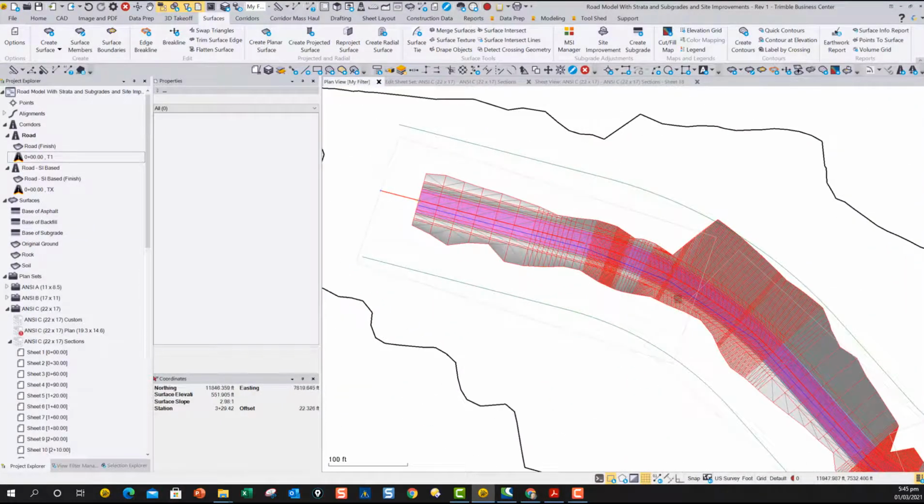And then I basically densified the models to get them all to match, because obviously on curves, when we're building it from surfaces, we need the surfaces to be accurate through the curve. So I basically densified all of those surfaces through here.